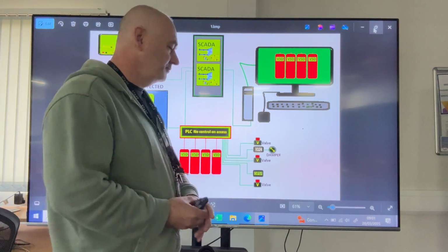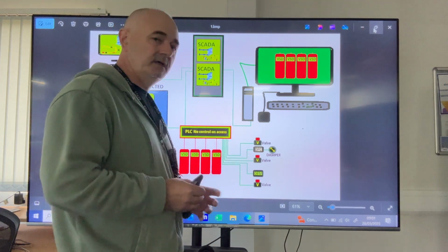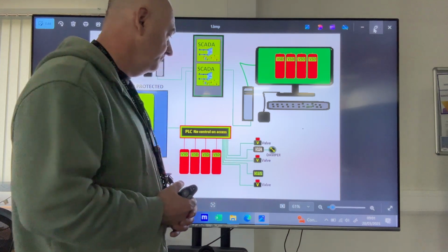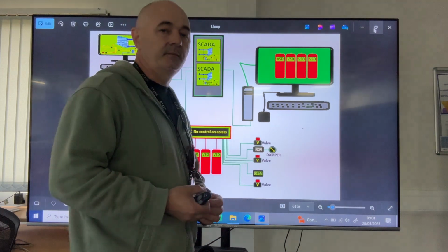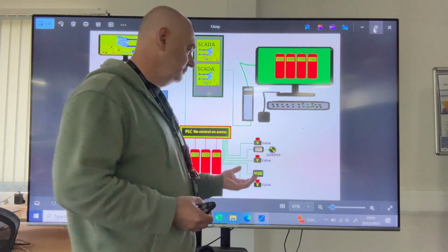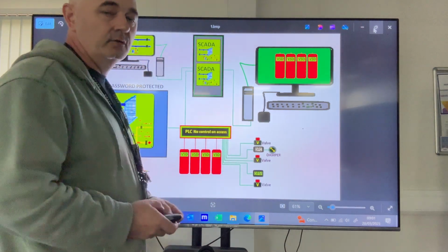We have differential pressure controls, which are electronic controls like microcomputers. People can change the set points, they're not protected. We have valves which can be manually manipulated, and there's nothing to capture their position, they're not trended. So we have a lot of problems with our control equipment.